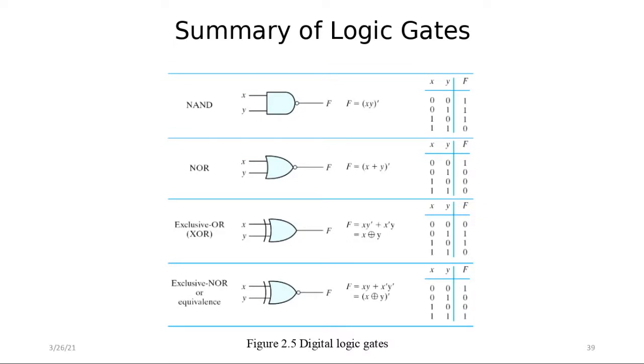This is just the opposite of the AND gate. And there is also NOR. This is also the opposite of the OR gate. There is also XOR. It's new. You have to memorize the XOR gate. If the inputs are the same, like 0, 0 or 1, 1, the result is 0. If the inputs are different, like 0, 1 or 1, 0, the output is 1. So it is just a kind of comparison of the inputs, right? We compare whether they are equal or not equal.